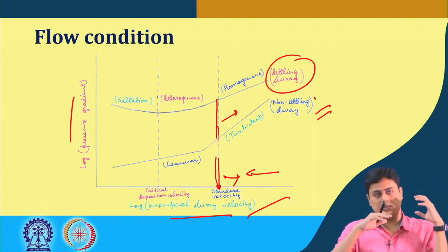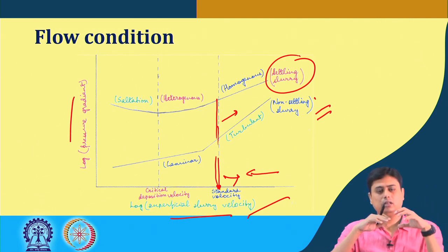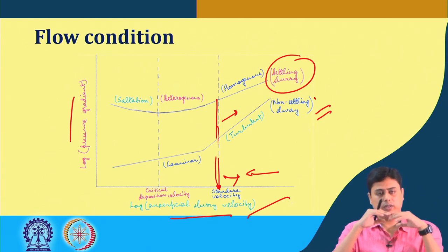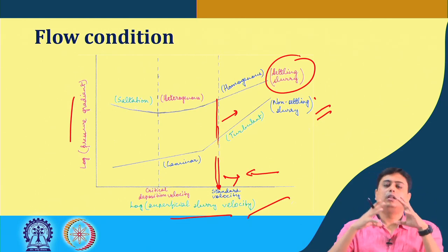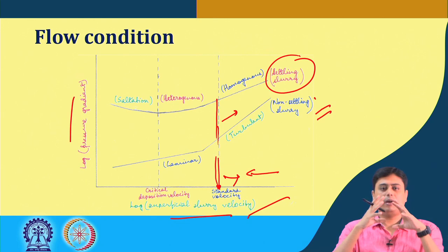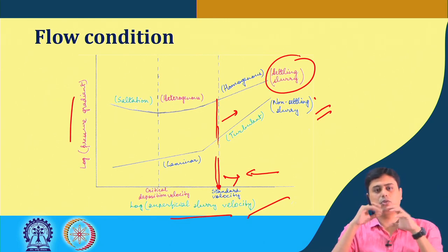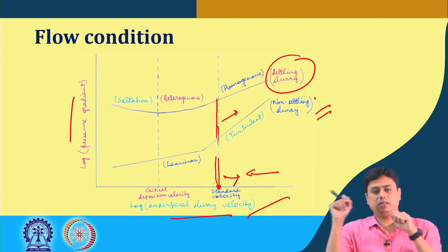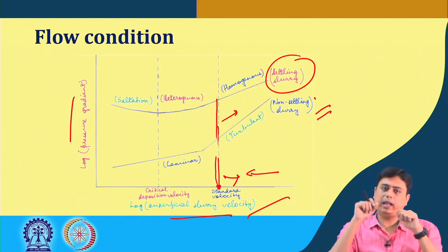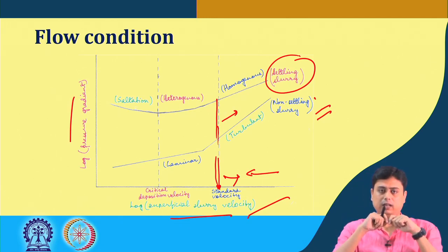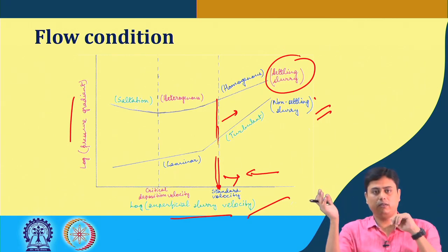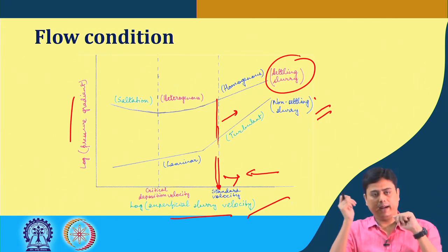That means at a very high velocity, all the settled particles get suspended again due to the chaotic motion, and the cross section would apparently have an even distribution of the solid particles. The point is the relative concept of the time it takes to reach a certain distance and the time it takes to settle. If within that time it reaches a certain distance, it can remain suspended for a longer time, and that happens here.